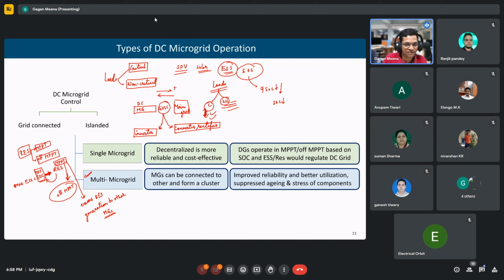Let's say this is P1, P2. What is this GVSC? This is the grid voltage source converter. It's a converter that allows bidirectional power flow. It can operate both as an inverter and as a rectifier. So for which power flow, P1 or P2, will it act as an inverter? P1, it is inverter. Yes, correct.